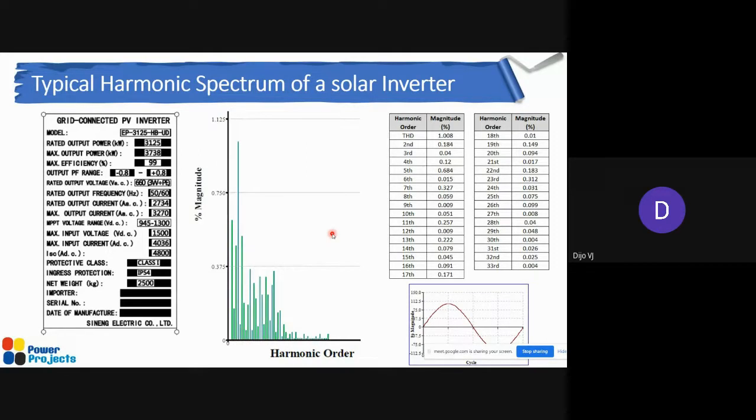But the EHV connection to the grid is at a location around 75 kilometers away from the solar plant, and because of that transmission line, harmonic injection gets reduced, because the transmission line capacitance itself will act as a sink for the harmonic content. And at the grid connection level, it is close to 5% or slightly more than 5%.